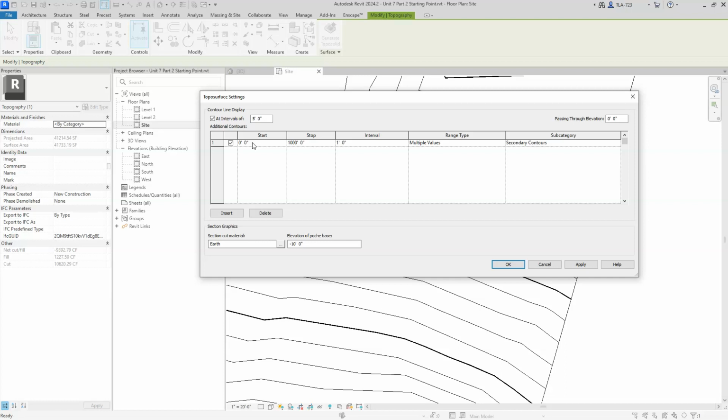But other projects, and I'm sure you've seen them or heard of them, they're going to set that main floor at 0. So you're going to have, especially on a property that's sloping away from the building, certainly a good portion of those contour lines below 0, or a negative number. So you first need to understand what your ground surface is doing and what elevation it is at, and then just create a range that encompasses that.